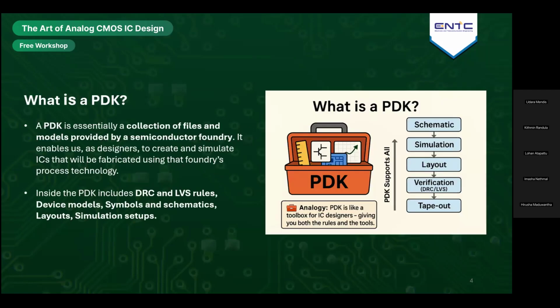Before we dive into the IHP PDK especially, let's first understand what a process design kit, or PDK, is and why it is so central to integrated circuit design. A PDK is essentially a collection of files and models provided by a semiconductor foundry. It enables us as designers to create and simulate ICs that will be fabricated using that foundry's process technology.